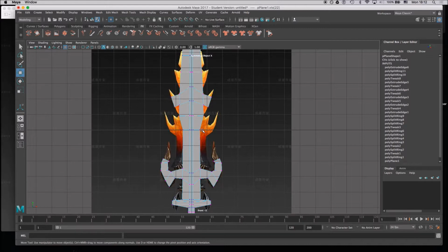So essentially a way to fix that is you go to Extrude settings, select all your faces. Then you go to mesh display, and normals. The black means it's the back, and then the gray is the front.